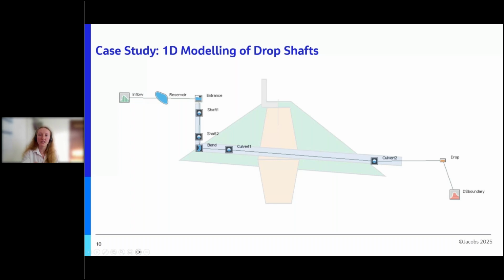Something to note with this schematic is that the culvert option gives head loss for the entire shaft, meaning we are overestimating losses if water level only comes part way up the shaft. An iterative process of changing the length of the vertical pipe is therefore needed so that the length of the vertical culvert matches the depth of water within the shaft. The reservoir option is preferential when modelling low flows, as it can deal with the shaft being dry, whereas you would always need flow through the system if using the culvert approach.